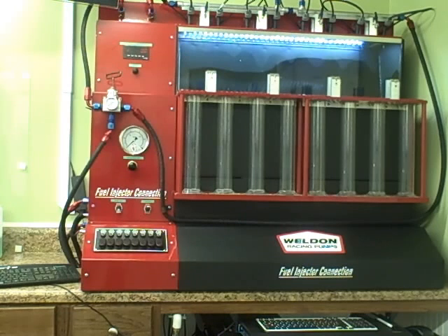With dynamic flow matching, we can get flow data electronically from the software from our data acquisition system that's built in the bench. The software has been created for our specs, written only for us, and written for our hardware. The pulse settings are controlled by a Megasquirt MS3 ECU, and we had some added software from them also. Once we can determine the flow rate per pulse, we can do several tests at different pulse widths and voltages. This enables us to get accurate theoretical dead times used for tuning.